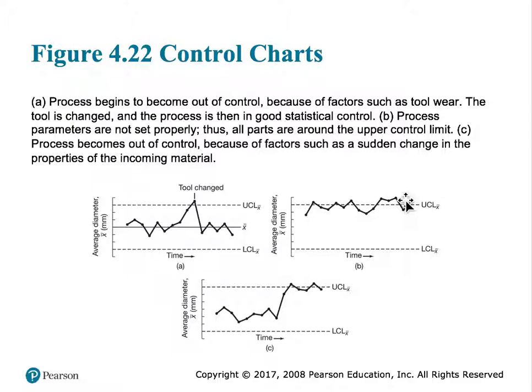By looking at the quality control charts, you will be able to determine whether or not your machining tool gave you the right kind of dimension, or whether that tool needs replacement. You might look at the quality control chart after every couple of hours, and it will tell you whether or not your tool is wearing out and how good your tool is to produce the parts within the limitations required.